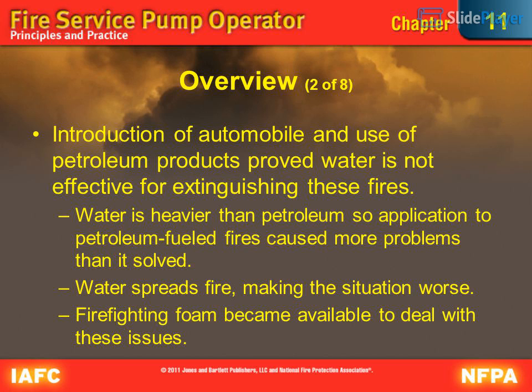Overview, 2 of 8. The introduction of the automobile and use of petroleum products proved water is not effective for extinguishing these fires. Water is heavier than petroleum, so application to petroleum-fueled fires caused more problems than it solved. Water spreads fire, making the situation worse. Firefighting foam became available to deal with these issues.